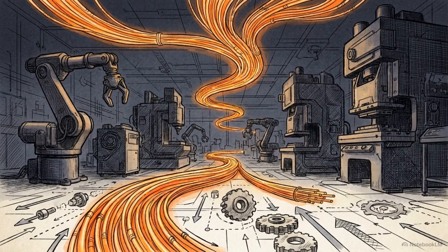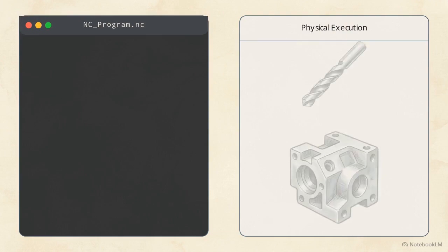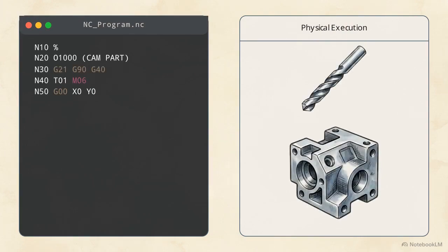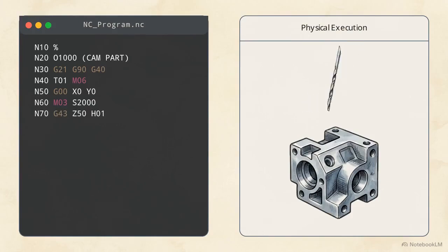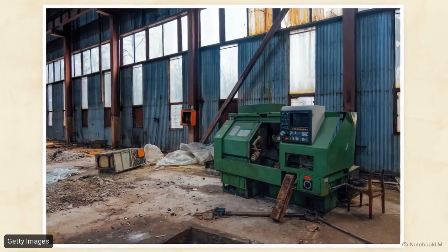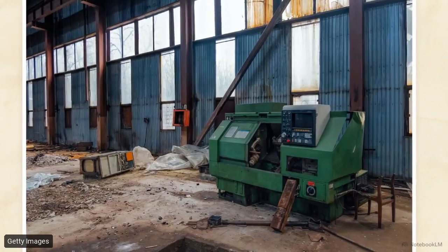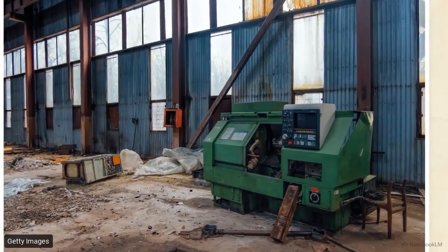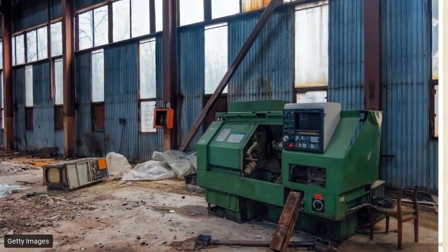With the routing plan formalized, the digital data moves out of the planning systems and enters the physical manufacture quadrant of the factory network. Computer-Aided Manufacturing, or CAM, translates the CAPP sequence into specific execution codes. These are highly specific instructions, like G-codes, that dictate the exact linear and rotational motion of cutting tools. These execution codes are fed directly into the physical hardware of the factory, the numerical control, or NC, machine tool.